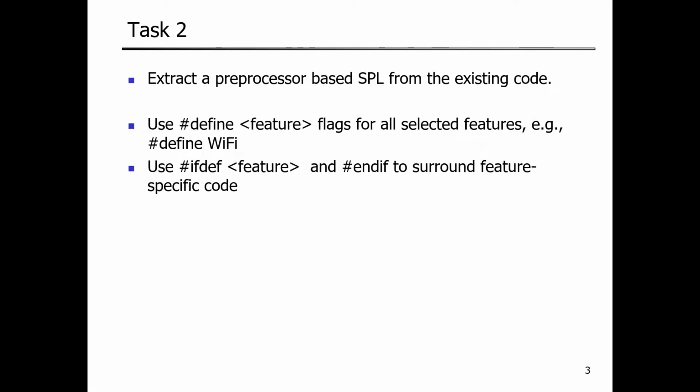Now let's move on. How do we actually implement this in our code, where we would then be able to extract all the different products from a common code base? We're going to use the define keywords and the ifdef keywords for macros in Arduino. The Arduino language is based on C, so it uses very similar keywords. So we use this ifdef from C. It's supported in Arduino.